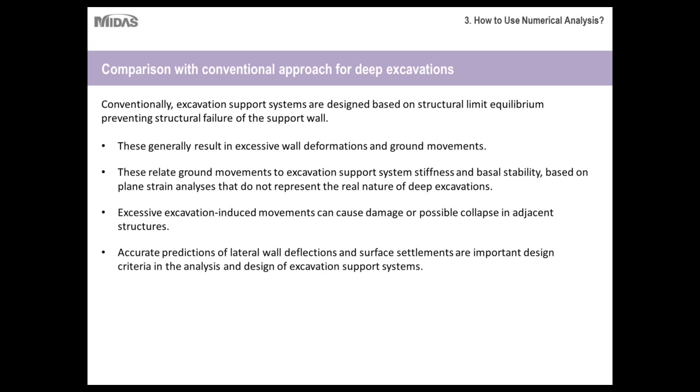So we have to accurately predict the lateral wall deflections and surface settlement, because these are important design criteria in the analysis and design of an excavation support system. Since everything boils down to the economy of the support system, you must accurately understand what forces are coming onto it and how optimally you can design it to make it an economical proposition.